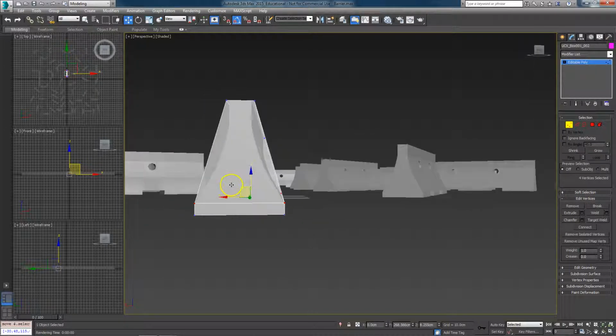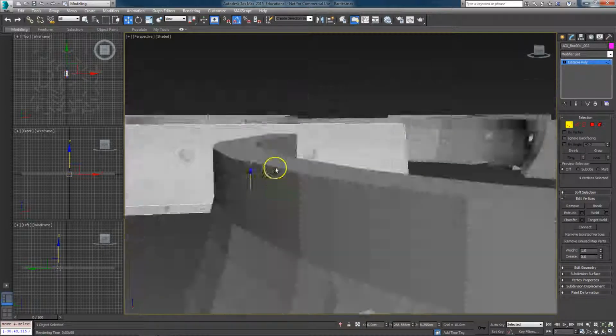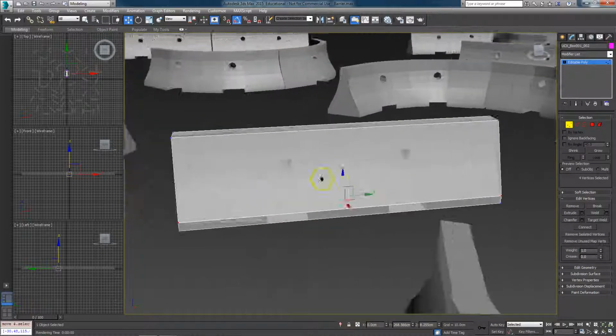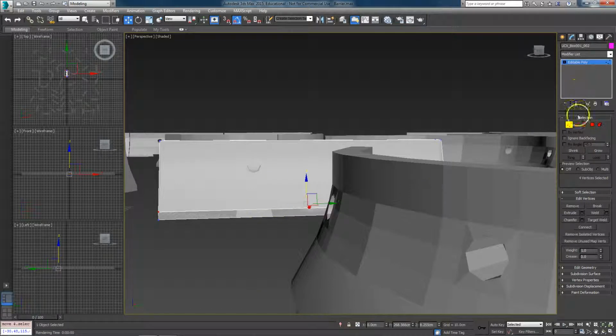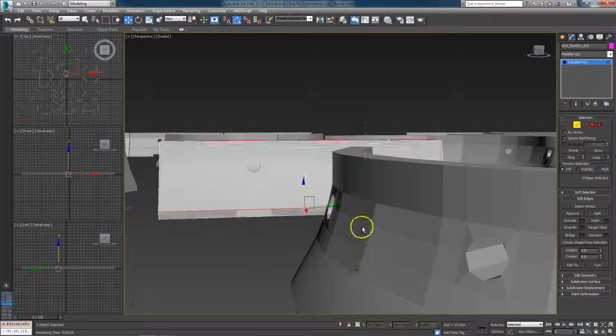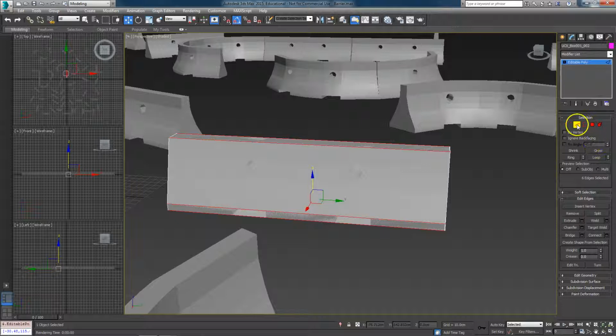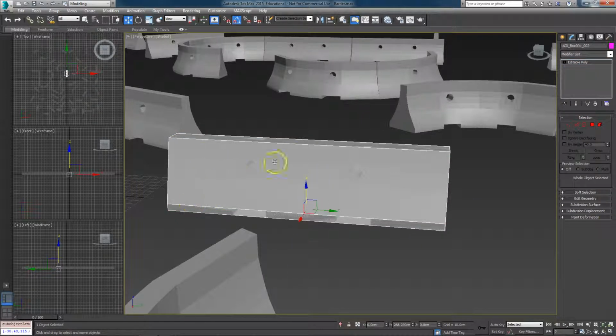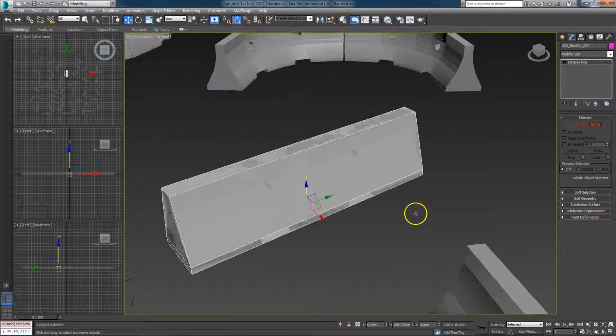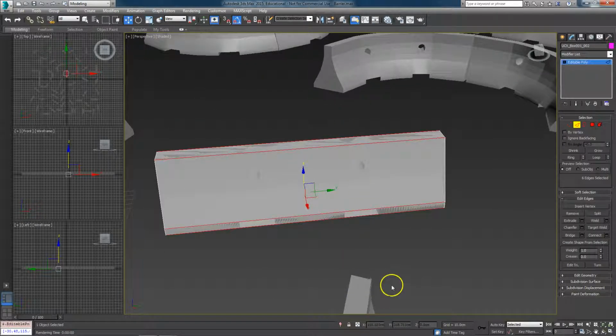And this will give me a cleaner collision doing it this way. And also, if I wanted to really have this get affected, I would end up coming here and creating multiple boxes like this. So I'd end up doing 1, 2, 3, so that way we can actually put forklifts under there. But just to box it out, let's create this real quick here.